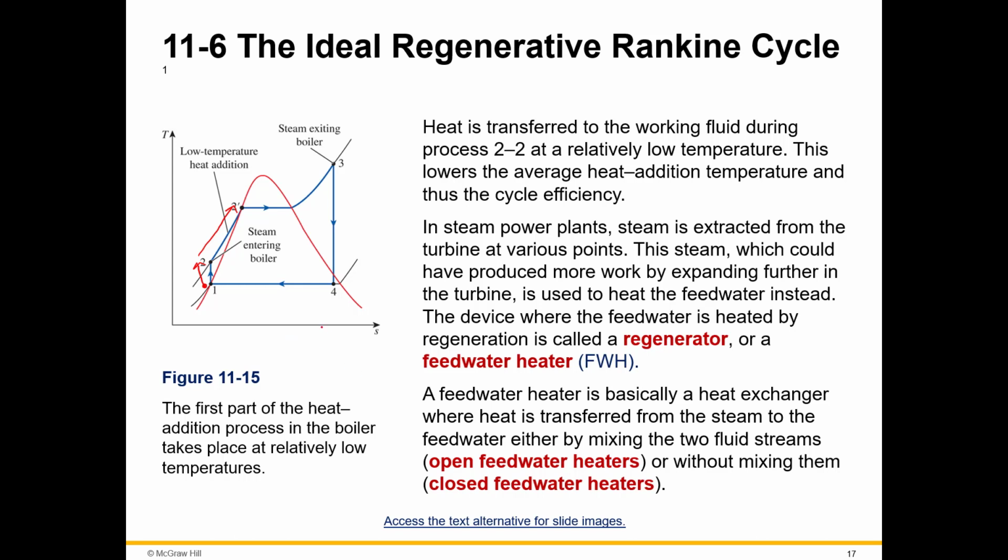So remember a couple of lectures ago we were talking about, well, maybe we can just power this shaft by robbing some power over here. That's what it's doing. So it's saying, hey, it does produce work, but we just can't have it here. Well, let's use it to heat the feed water instead. And this device, where the feed water is heated by the regeneration, is called the regenerator or a feed water heater. And you'll see that a lot.